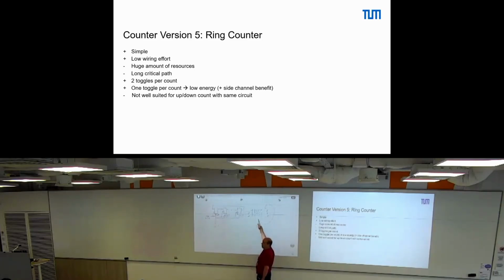What are benefits, drawbacks of this? We can be super fast because we always shift only one bit without any logic in between. It is pretty low power because we have no logic there, and we always flip only 2 flip-flops, nothing else. The rest is stable, so no dynamic power consumption.